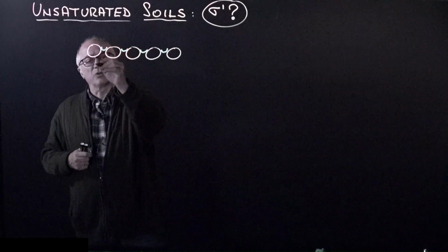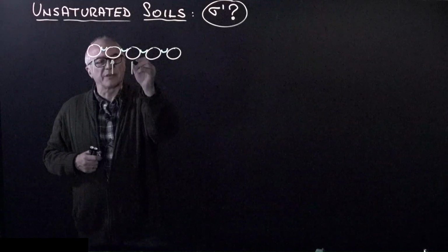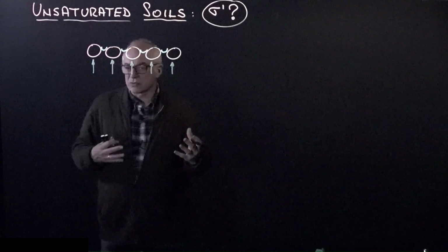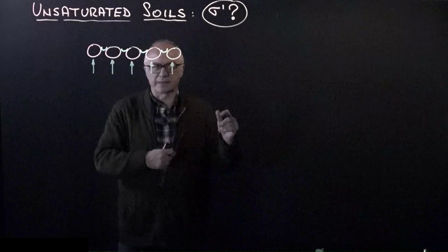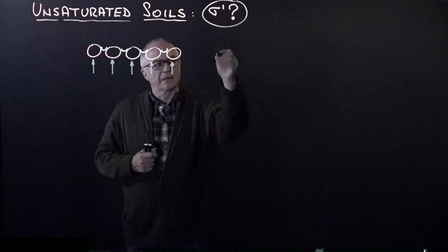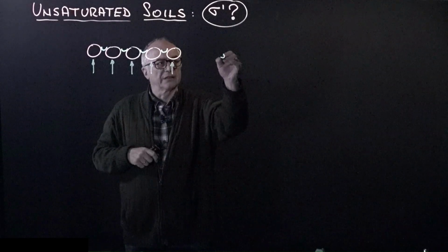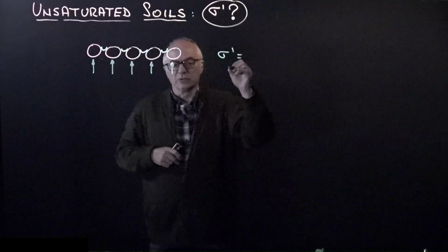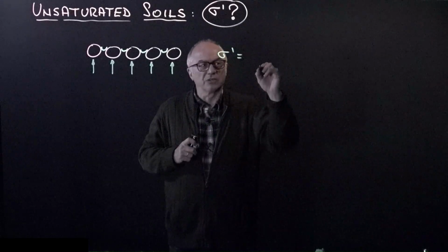So then we wonder, what are the forces that are going to be experienced by the skeleton and that will cause compaction and shear strength, etc.? So the question is, what is the effective stress? Under this particular condition, the effective stress would be equal, to a first order approximation, and we'll see how good this is,